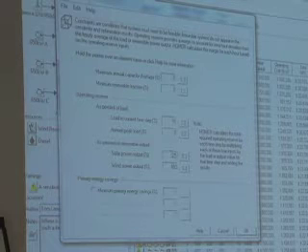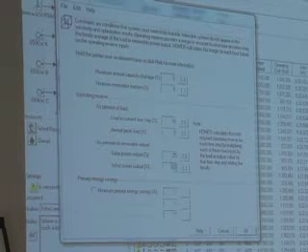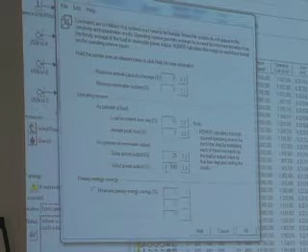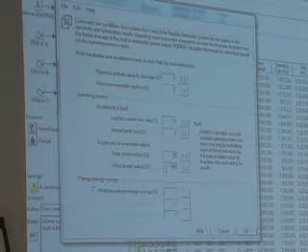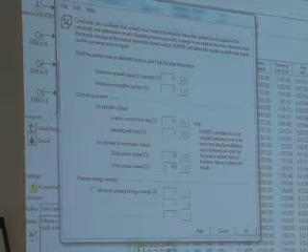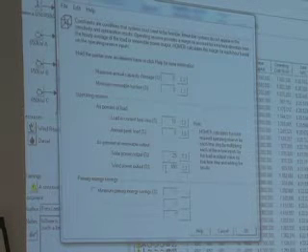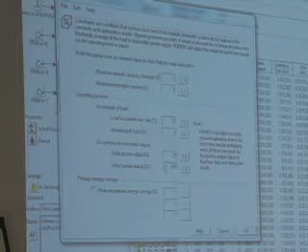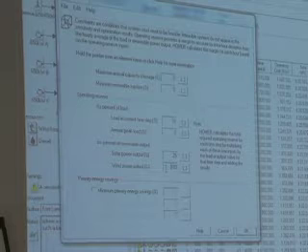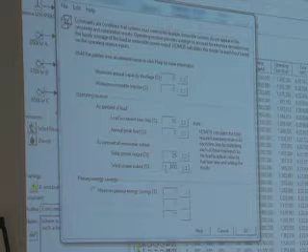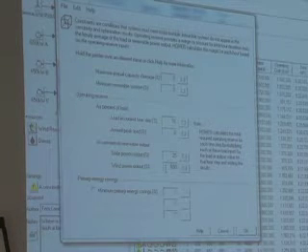Solar we're not going to talk about very much, but this is the key one, and a way to think about this is: within a particular time step, whether it's 60 minutes, 15 minutes, 1 minute, whatever, what's the maximum amount of wind power that we want to protect ourselves from losing? Russell said he's seen situations where you lose it all in 2 seconds. I'm hoping and presuming that's an extreme example. But if that was the case, you'd want to put 100% there.